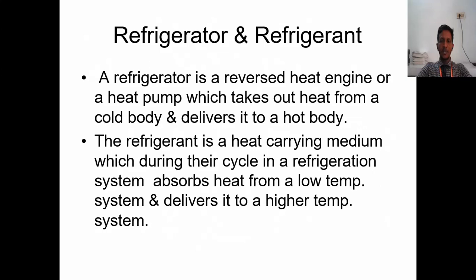And the refrigerator and the refrigerant. The device which is used to carry out the refrigeration process may be called a refrigerator. The refrigerator is a reverse heat engine or heat pump which takes out heat from a cold body and delivers it to the hot body. Okay. The refrigerant is a heat carrying medium. The medium may be fluid, air, or whatever liquid medium we can use. The refrigerant is a heat carrying medium which, during its cycle in the refrigeration system, absorbs heat from a low temperature system and delivers it to a higher temperature system. Okay.